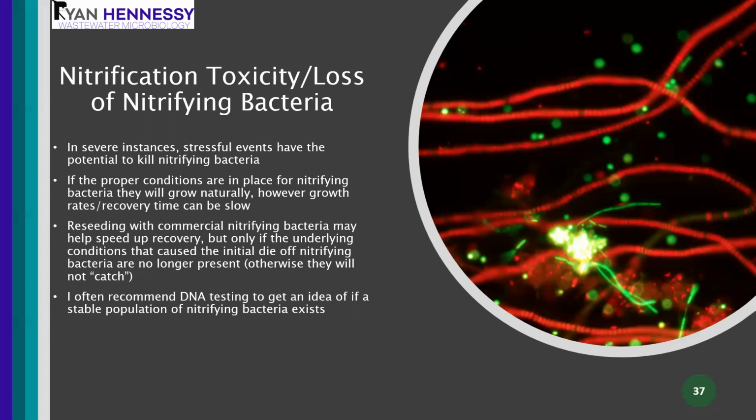Now, however, it's also really important, because if there's something that stressed out your original nitrifiers and you reseed with more nitrifiers, if you still have that stress there, they're going to have the same fate as the previous nitrifiers. So you can bioaugment with nitrifying bacteria, and it is successful if the conditions are right. I have seen where it decreases the recovery time, sometimes by a day or two.